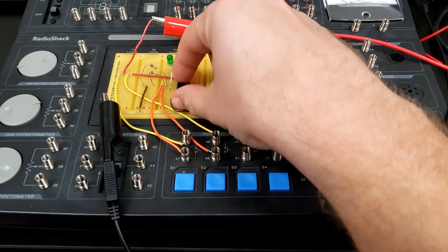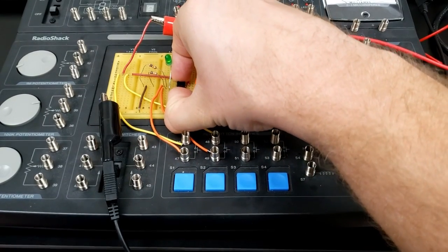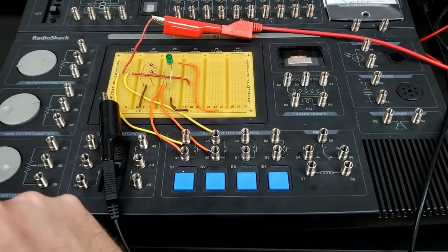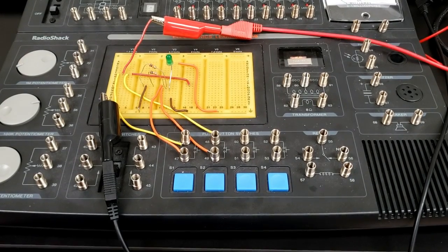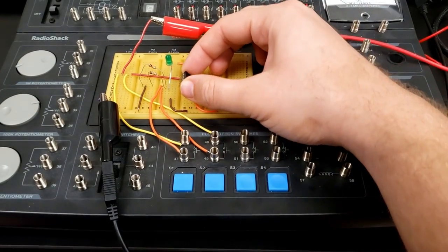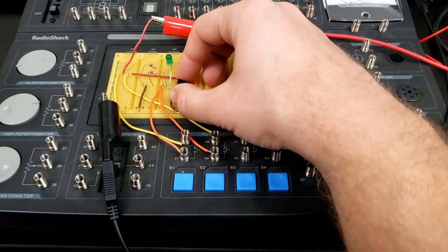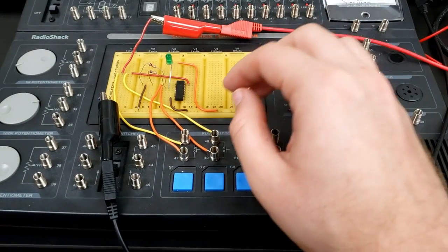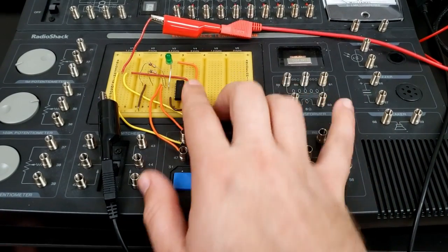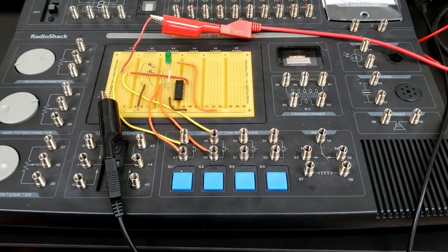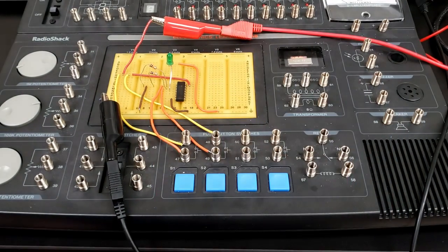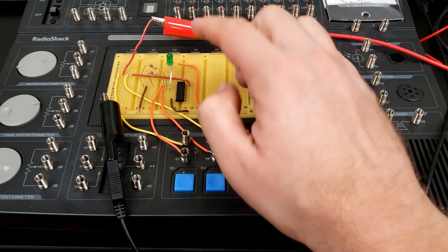So now let's go ahead and replace this circuit here. So we'll put even pressure on either end of it by pulling it out. And we're going to replace it with a 4011, so a 4011 integrated circuit is going to go in next. Okay, so that should be good there. You can see that we do have the LEDs being lit up. So let's go ahead and do our truth table for this one and figure out what this guy is going to be here.